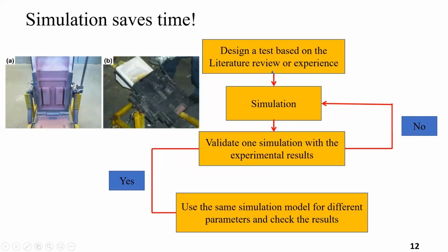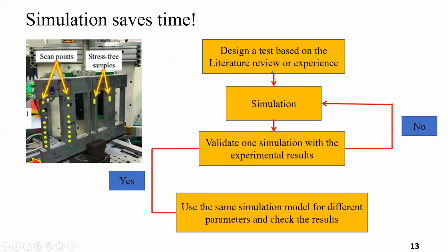Then we do a casting. I mean, cast the part because the part was very simple, and do the experimental test to see the residual stress distribution at the point of interest. So we did the simulation, we have the experimental result as well, right?